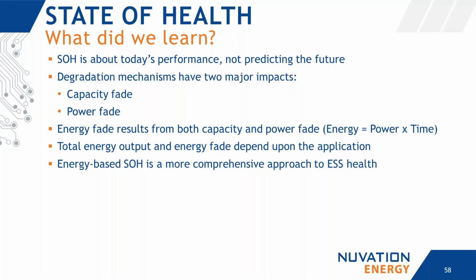A battery at the same quote unquote state of health in an amp hour sense may perform differently for different applications. So really we think that energy-based SOH is a better and more comprehensive metric to apply to energy storage systems when you need to think about end application performance.